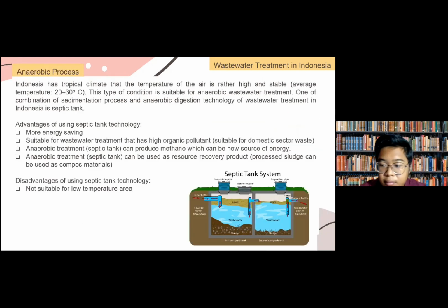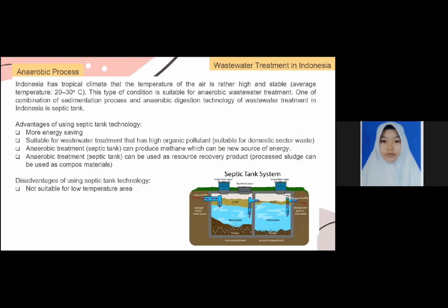The next one is about the anaerobic process. Indonesia has a tropical climate where the air temperature is rather high and stable, with an average temperature of about 20 to 30 degrees Celsius. This type of condition is suitable for anaerobic wastewater treatment. One combination of sedimentation process and anaerobic digestion technology for wastewater treatment in Indonesia is the septic tank.